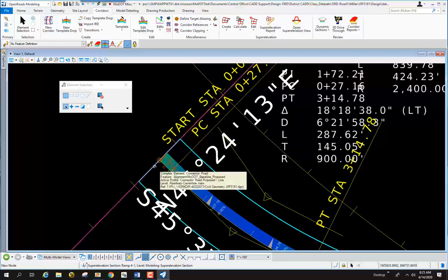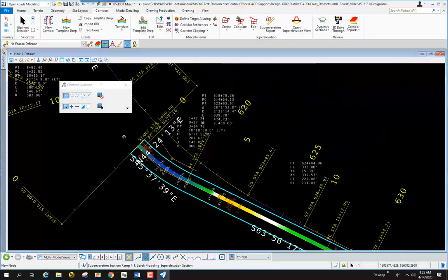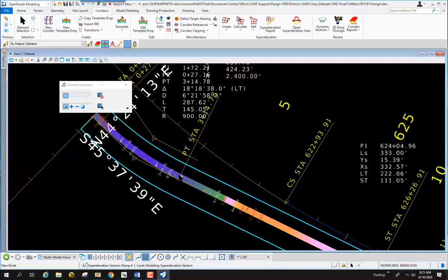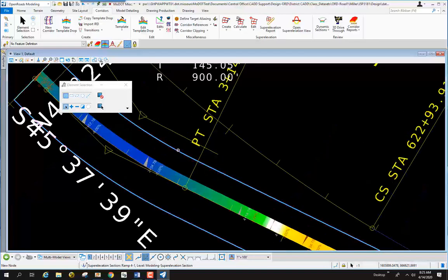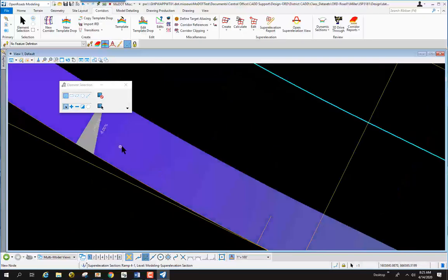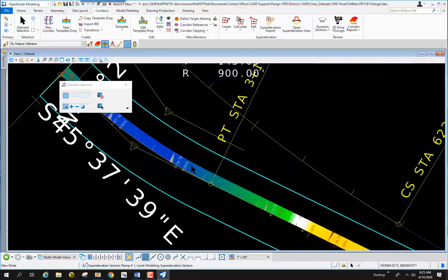Okay. Now on page 633, step 15, it's just stating that all those edits that we did, whether it was in the superelevation editor or the profile, could all have been done by just coming into this file here, clicking on the section and modifying the heads up settings that we have on this shape. So everything we did before could be done in this view here.